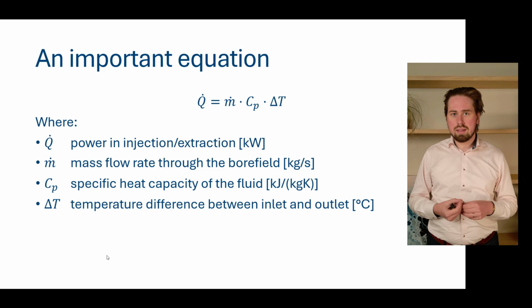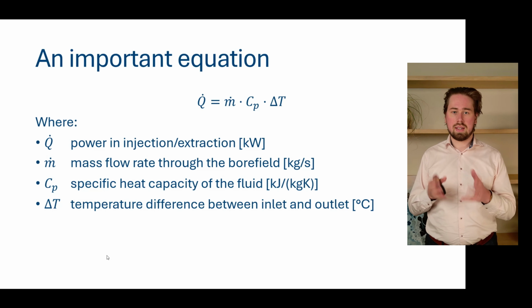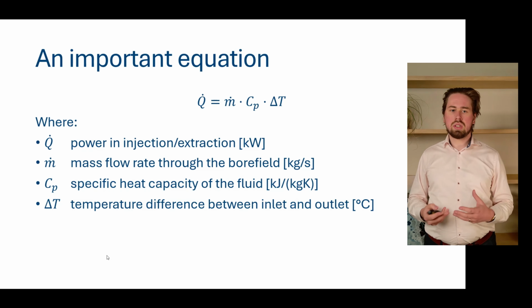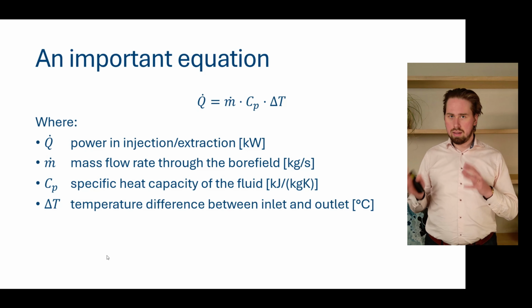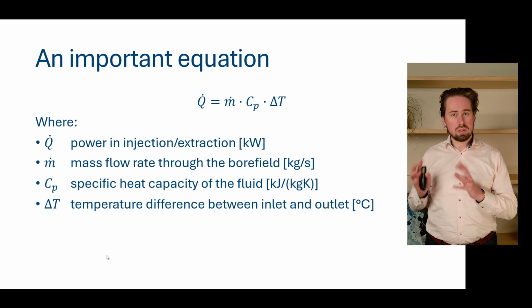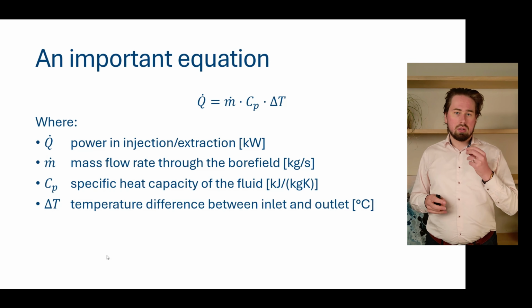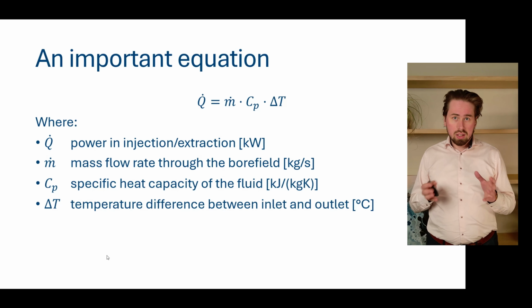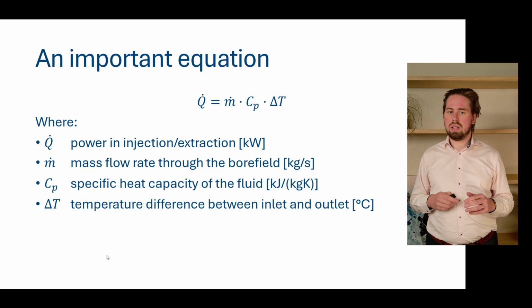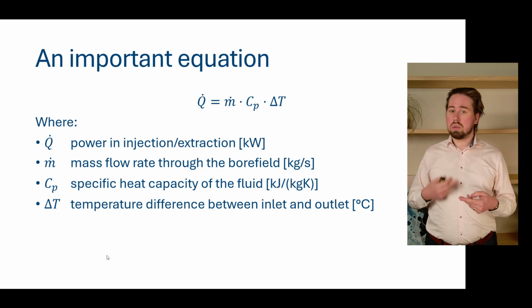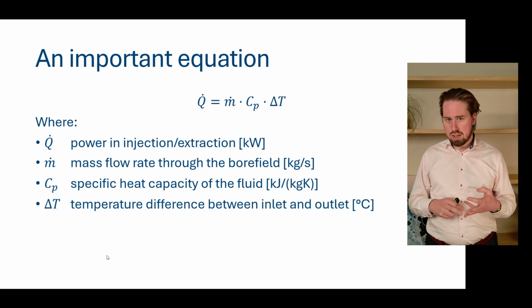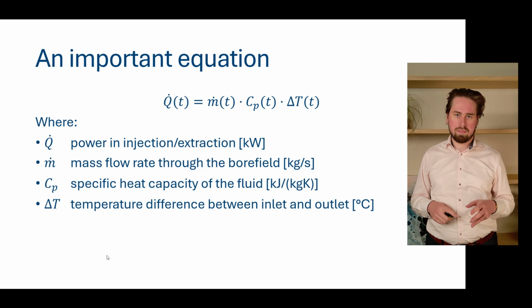Now today we will be looking at a different aspect, namely variable flow rates. To understand this, we have to look at a very important equation in the whole of heat transfer, basically. It's given here on the slide. It's the relationship between power on the one hand and the flow rate, the heat capacity, and the temperature difference between inlet and outlet on the other. Now, one thing we need to do first is, this is not an equation of constants, because your power can change over time, and so can your flow rate and your temperature difference. So let's make this time dependent.